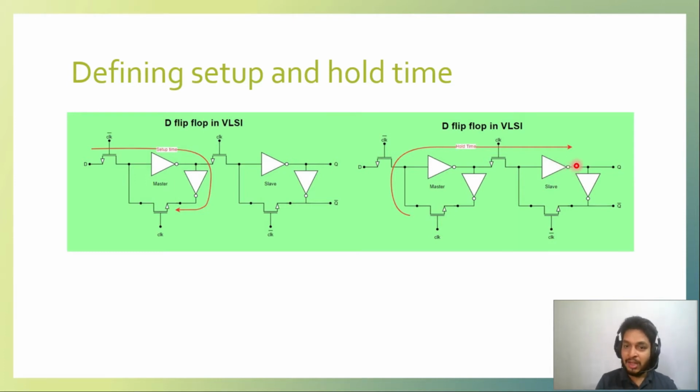So imagine that the data is propagating, it went to the output of this inverter, and immediately the data has been changed at this input, and that makes some kind of disturbance to this input, because there is already propagating data and this new data also comes in. If the data which is going is 0, and the data which comes is 1, then there is an ambiguity at this line about which data has to be transferred, right?